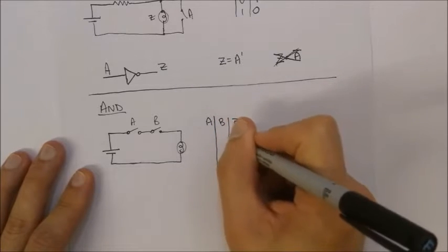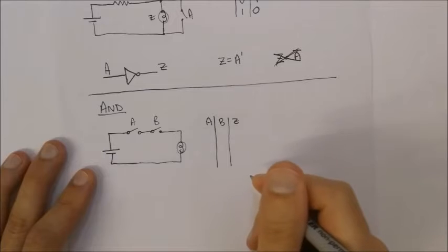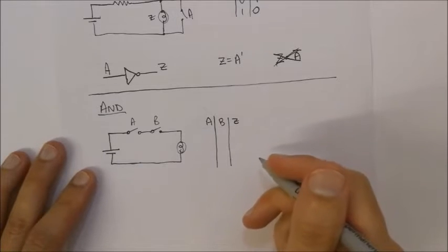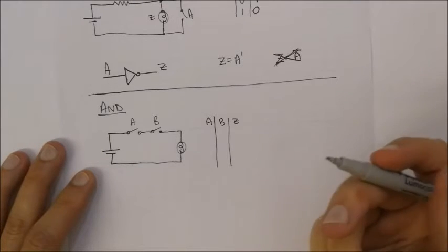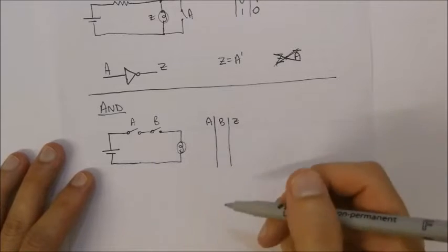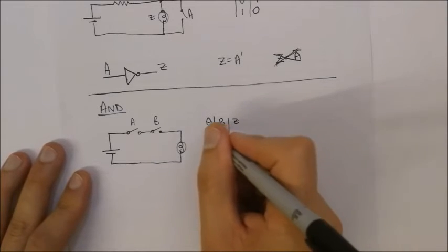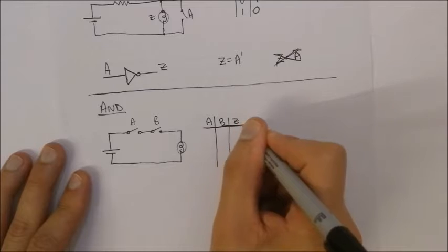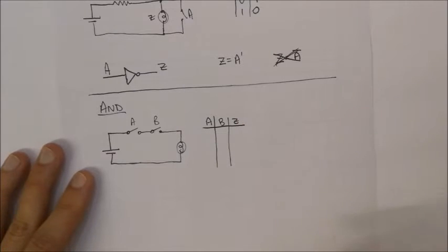Okay, now depending on the number of inputs, the different options come down to 2 to the power of n. We've got two inputs, so 2 to the power of 2 is 4 different options available. And essentially we're going to be counting in binary.